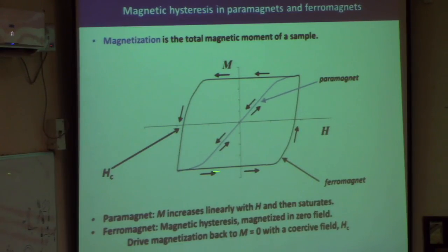And then what you can do is cycle around again by magnetising, demagnetising, and so on and so forth, so that you generate a series of loops. And these loops are referred to as hysteresis loops. This term hysteresis, as the name implies, is connected to the history of the sample. That means the current state of your material depends on what's happened to it in the past. It is magnetised here because previously you've applied a field to it.